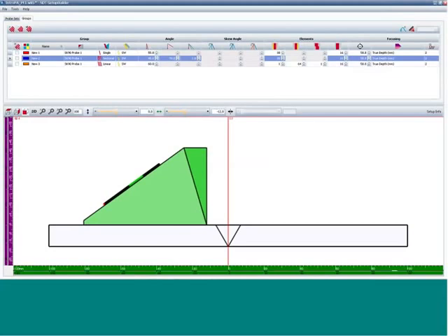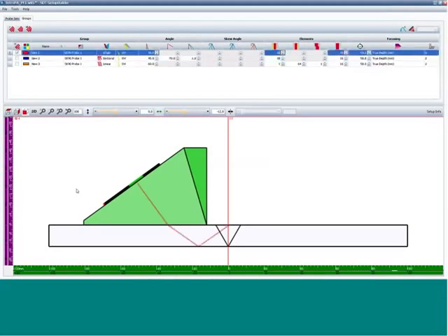So if we look at a single group that includes one static A-scan here, to put in play some of the terminology we talked about, the single A-scan is being developed from our phased array probe 1. We are asking for a shear wave velocity refracted angle in the material of 55 degrees. I can change that angle directly in the calculator.